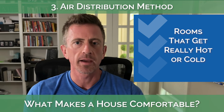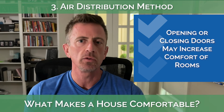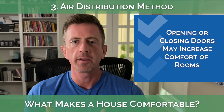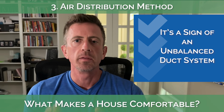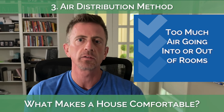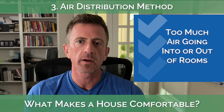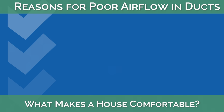You might have a room in your house that gets really hot or really cold at different points in the year, and you may even notice if you open or close a door to that room that it significantly improves the comfort inside there. This is a sign of an unbalanced duct system, meaning that either too much air is going into that room or too much air is going out of that room, and this happens for a variety of reasons.